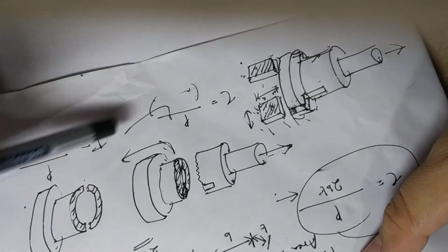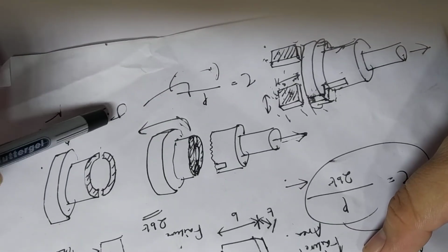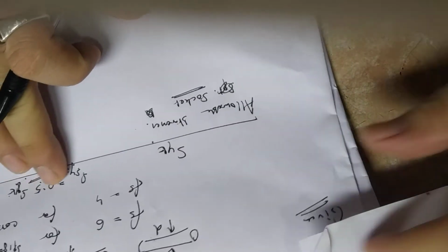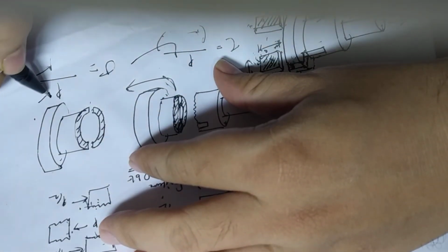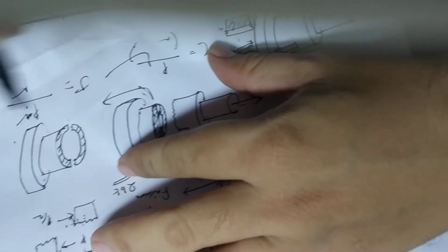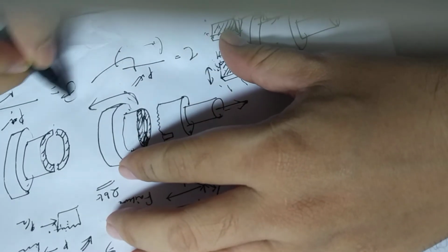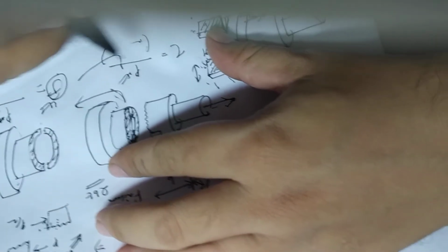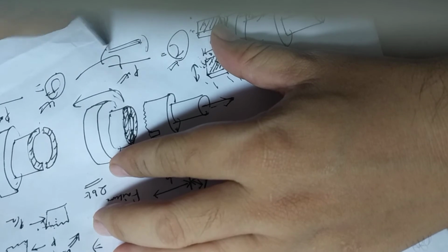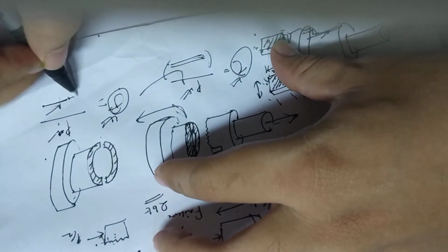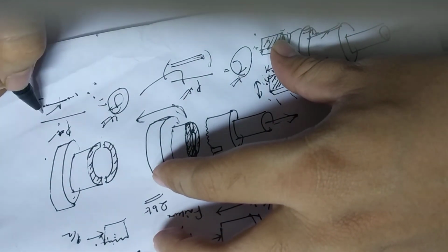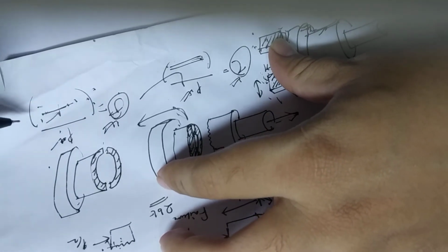Forget about crushing or compressive failure here. We'll do only tensile and shear. Since P, the applied force, is given, we have to find the allowable stresses, and from the area formulas we get the dimensions, because areas comprise the dimensions.